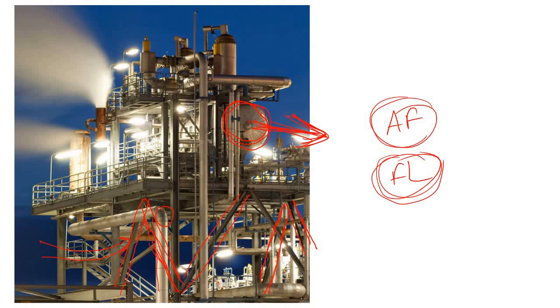Not only that, as you can see here, this whole system is simply acting like a wall. When the wind is coming from this direction or the earthquake is coming from this direction, this huge mass creates a huge lateral load in this direction. To carry this, we need this setup of bracing.